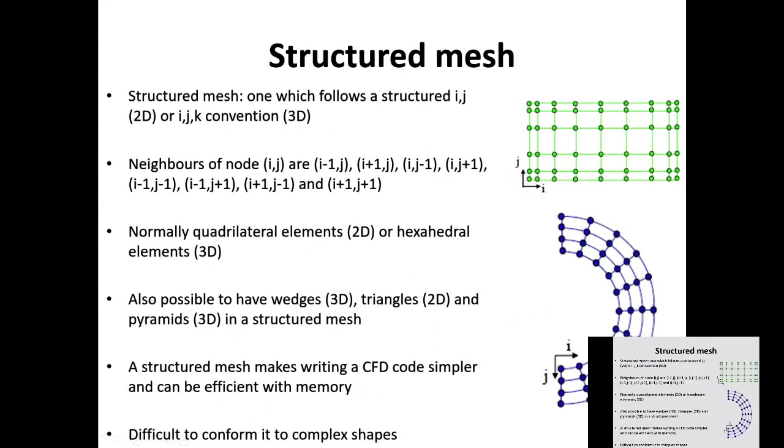And then you look at meshes: structured meshes and unstructured meshes. In a structured mesh, when you take an edge from one side and go to the other side of that, you will have the same number of grid nodes. That's a structured one. When you take that side and that side, you will have the same number of nodes. So this is a structured grid. This is also a structured grid. If it is unstructured, you don't have the same number of grid nodes on the edges.